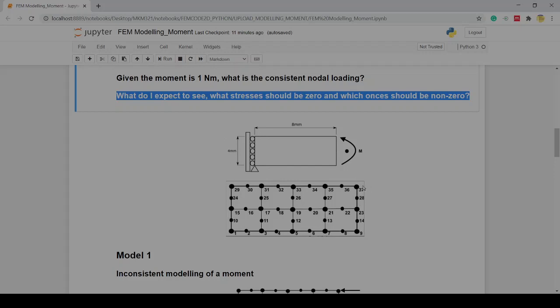So I can imagine that if I have a force pushing at this side of, let's say, 250, and I multiply by 2, that is a moment of 500. This one will be in the same direction, so I have another 250 pulling here, a distance of 2, is another 500, so 500 plus 500 Newton millimeters. That's 1000 Newton millimeters, and that's the same as 1 Newton meter. So we expect to see a load of 250 newtons pushing here and 250 newtons pulling, because that will be 1000 Newton millimeters, which is the same as 1 Newton meter. That's what we need to make sure of.